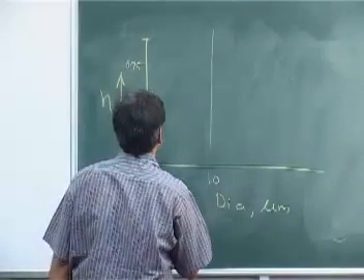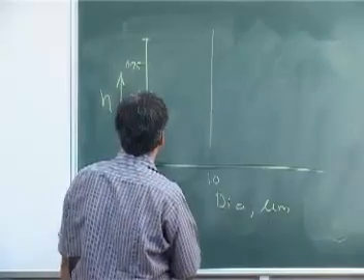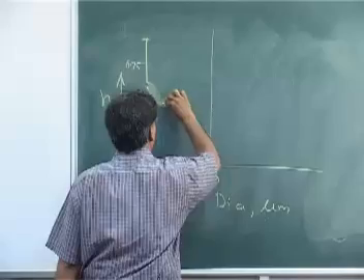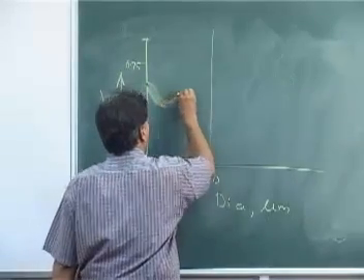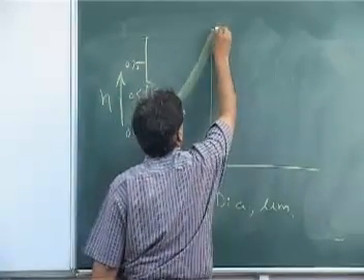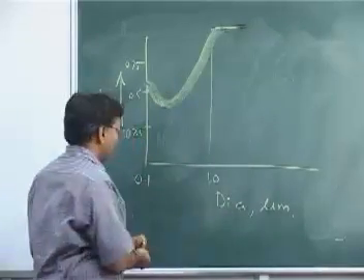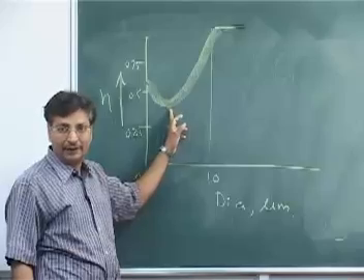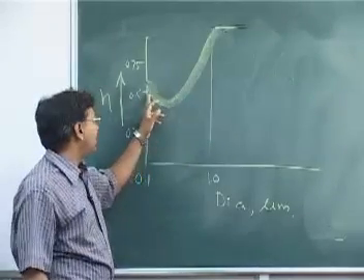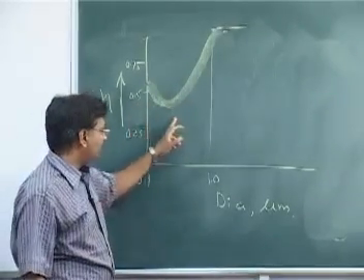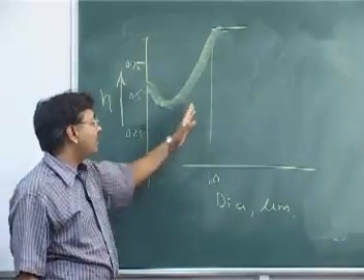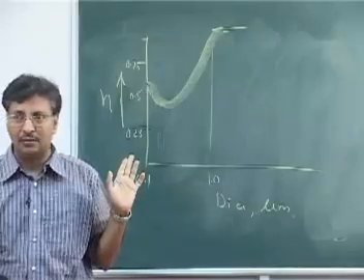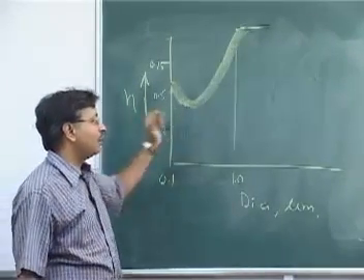So this efficiency looks something like this. This is a band basically. So some particles between 0.1 and 1 micron have the minimum efficiency. Okay, and the smaller particles will have this, and then you see almost any particle with a size of 1 micron and above will be removed 100% in your ESP. But some particles may have some lower efficiency.